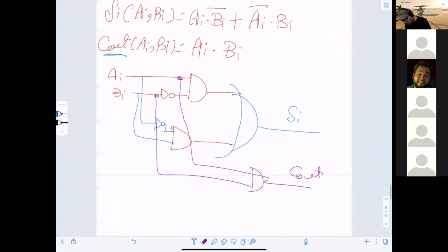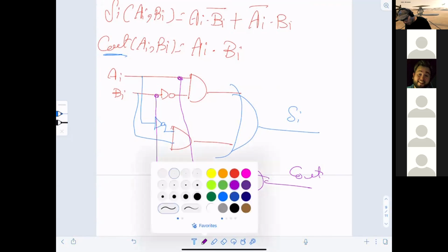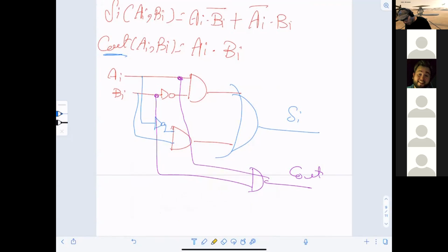Now there is something in the aspects we need to discuss, which is critical path timing here, right? Even though we said it's a combinational circuit that doesn't have a sequential element for generating a clock, on top of that we are looking for the critical path. Our critical path in this case is the longest path between input and output.